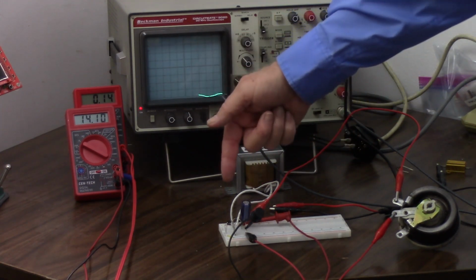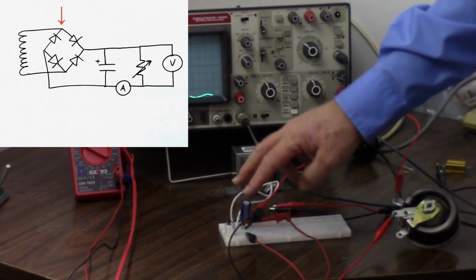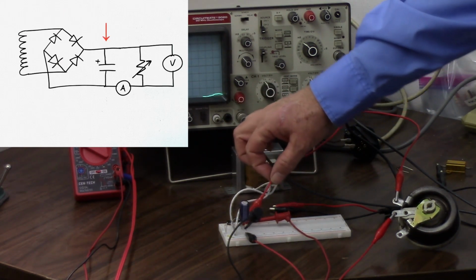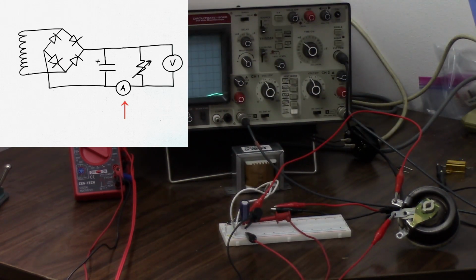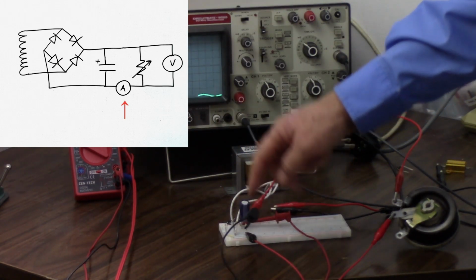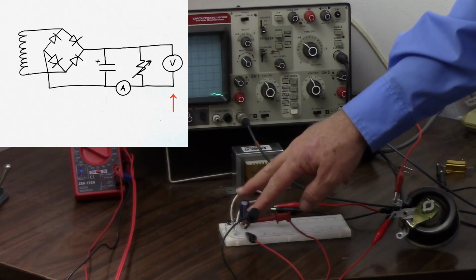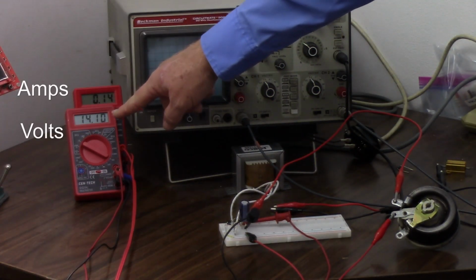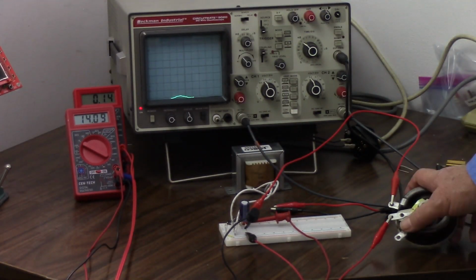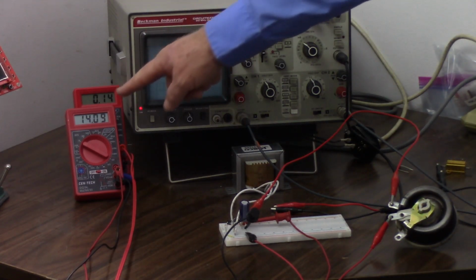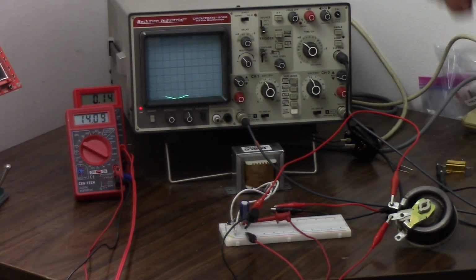So I have the transformer coming into the rectifier, that's going to the filter as you've seen before. Coming off the filter, I'm coming to my load, from my load through my current meter up here, down to ground, and then I have my voltmeter across the capacitor. And as we can see with about 100 ohm load, I have 140 milliamps and about 14 volts. Now what I'm going to do is increase my load until that drops down to 12.5 volts and see how much current that is. Now I've been cheating all along here.